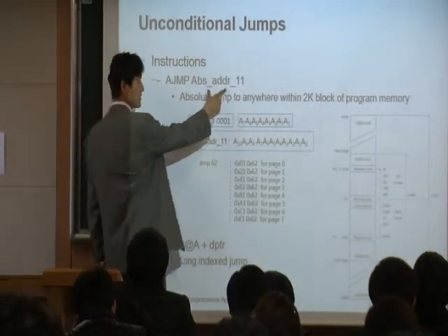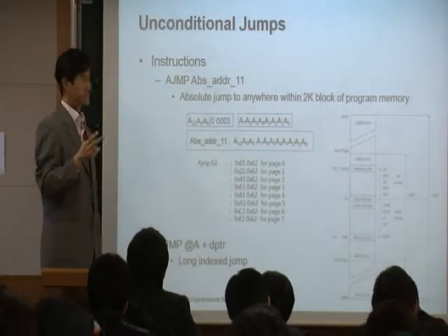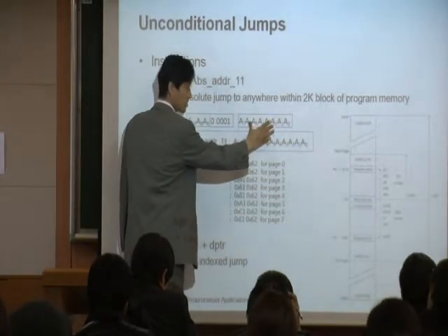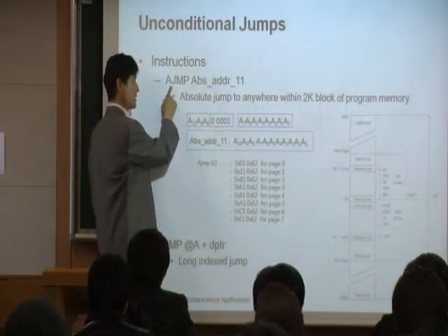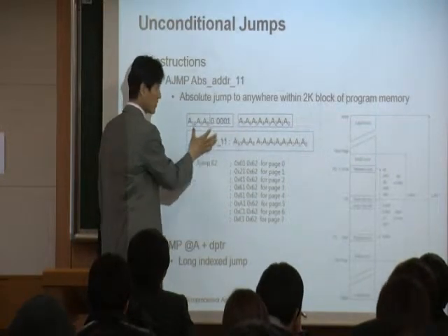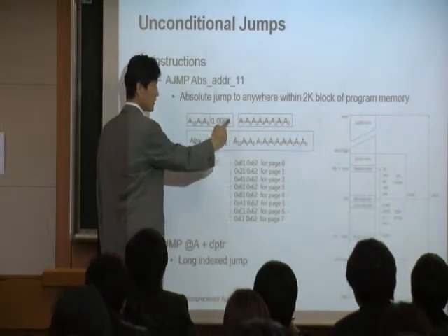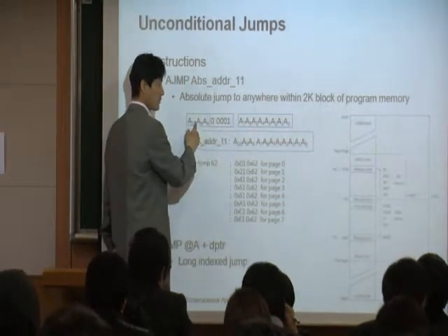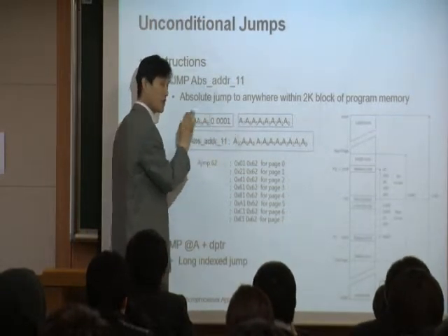And how do you make 11 bits? Again, this instruction is a 2-byte instruction. We have only 2 bytes. The second byte here is the operand, with 8 bits. And interestingly, this instruction has an additional 3 bits in the first byte as operand. In the first byte we have 8 bits, and out of these 8 bits, the last 5 bits are the opcode.